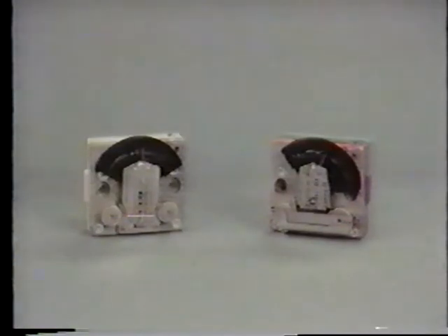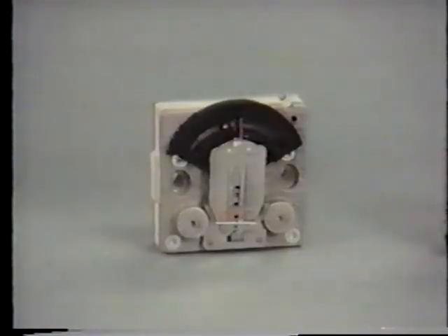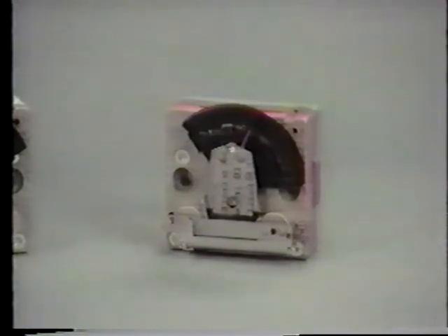The summer-winter thermostats come in two models: the single bimetal for the same set point, summer and winter, and a dual bimetal to accommodate different set points for summer and winter. This is the single bimetal summer-winter thermostat. Notice that this thermostat has only one bimetal and looks very much like the single pressure models. This is the energy conservation model, summer-winter thermostat. Notice it's a dual bimetal model with two set point adjustments.